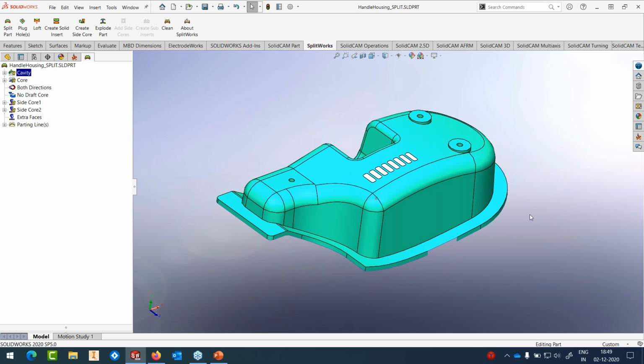It's a very important aspect in the entire process to create the right parting surface so that manufacturing becomes much easier. When you're creating a parting surface, we always have to keep in mind the machining process. Creating too many sharp corners will either create the need of making more electrodes or using tools like a flat end mill to get closer to the sharp corner. So we try and avoid sharp corner situations in parting surfaces as much as possible. But sometimes they're not avoidable. Sometimes they need to be created.